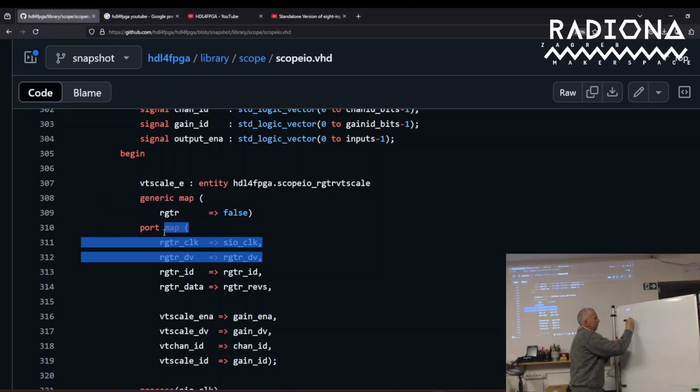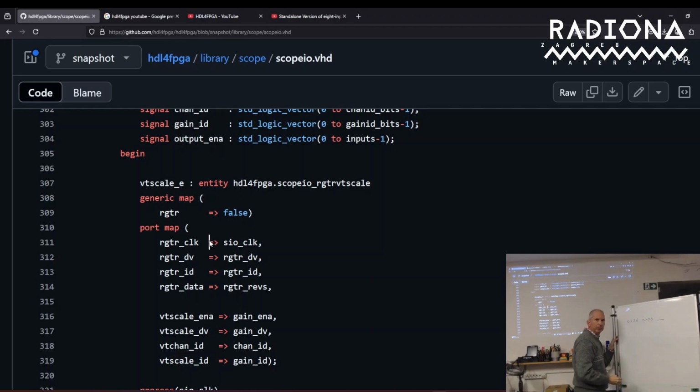The first is the register number, for example, let's say 160, then the size. You always have to add 1 or subtract 1 depending on how you see it, but if this is 0, that means there will be only 1 byte, and then comes the payload. So this is simpler. If you need something with more bytes, you only need to change this.